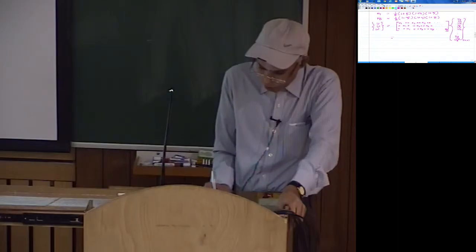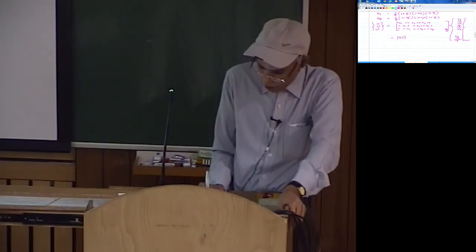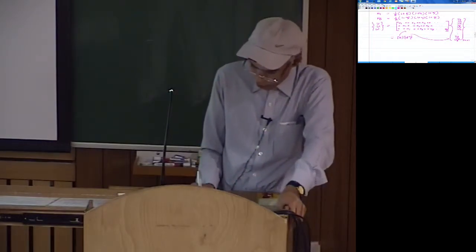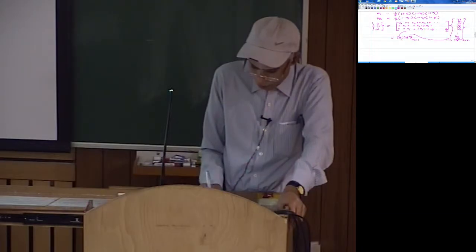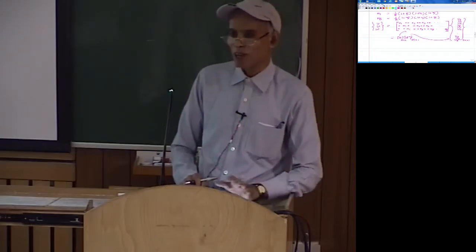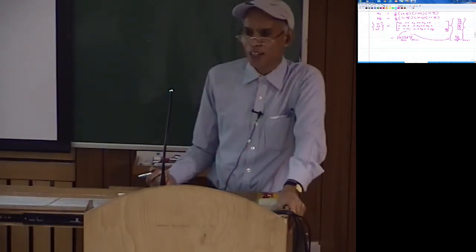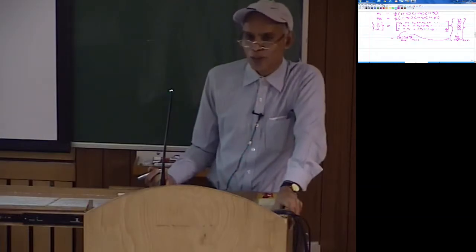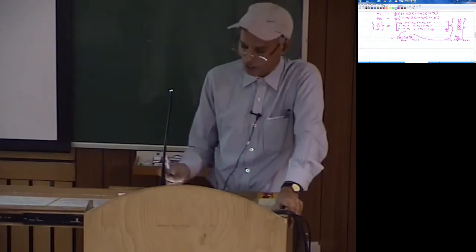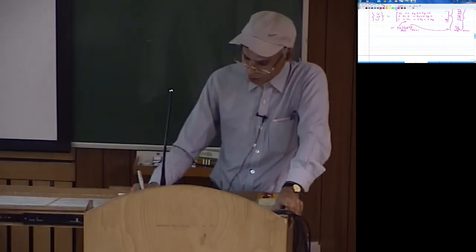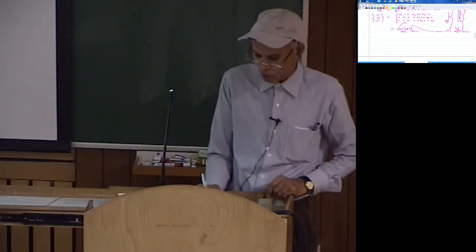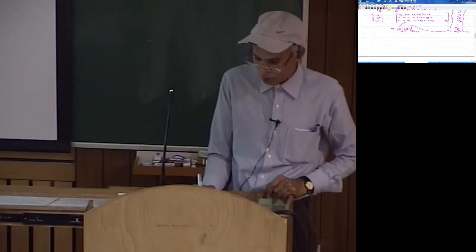So this, as usual, you call it the interpolation matrix H, and this has the vector of elemental degrees of freedom d^e. And this is your H, as we have said, this is 24 by 1 and this is a 3 by 24 H matrix. So obviously you see these cannot be done manually. If you want to solve problems, you have to write a code or use a package, because the sizes of the matrices, multiplications and calculations are too many. So only we can conceptually look at how the formulation is done. So this u, v, w are expressed in terms of interpolation matrix H and the vector of elemental degrees of freedom d^e like this.